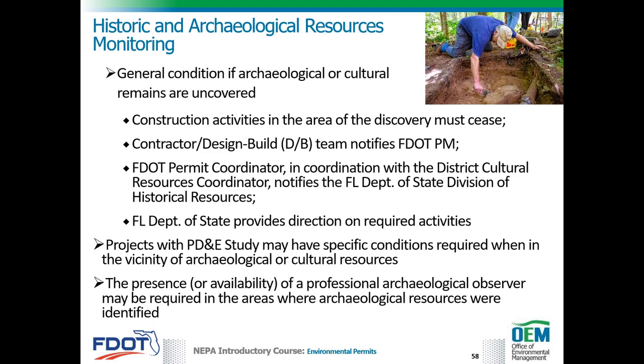All state ERPs and Section 404 dredge and fill standard permits include a general condition prescribing actions that must occur if archaeological or cultural remains are uncovered during construction activities for an FDOT project. Generally, the following actions are required. Construction activities in the area of the discovery must cease.